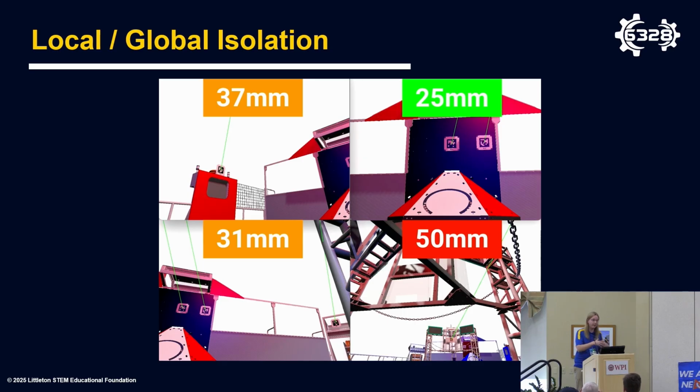Remember, AprilTags tend to be very evenly distributed around the robot. But here, when we're looking at the speaker and trying to shoot, we want to be using local positioning relative to that field object. And here, you can see the filtering object is trusting those speaker tags more. That's not because it has identified those specific tags as ones to be trusted, but just because our cameras are positioned in such a way that those tags are clear and large in the frame. So it would want to trust them anyway, implicitly.